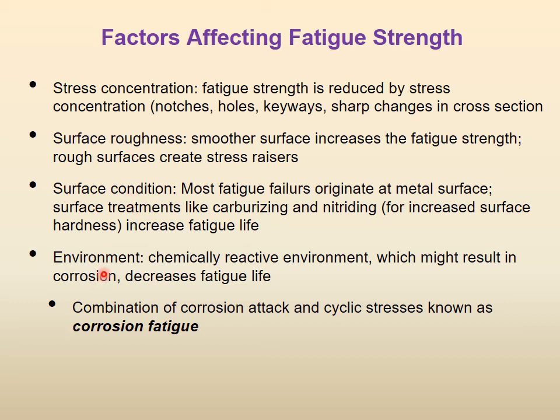Environment. In what type of environment are they working? Is there a chemically reactive environment which might result in corrosion, right? So if there is water or water vapor or dampness around, if there is salt or something around, then fatigue life will be decreased because of corrosion, right? If there is a combination of corrosion and fatigue, cyclic stress, then it is called corrosion fatigue, right?